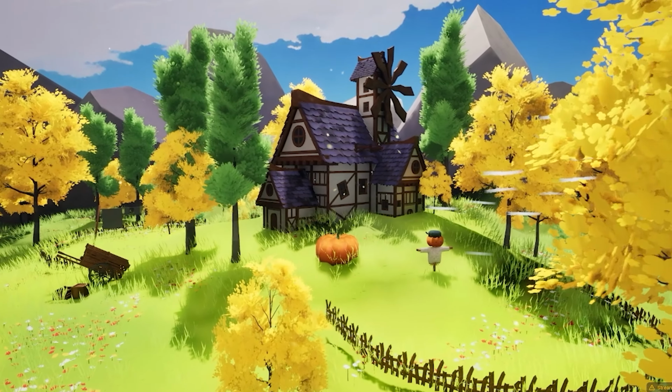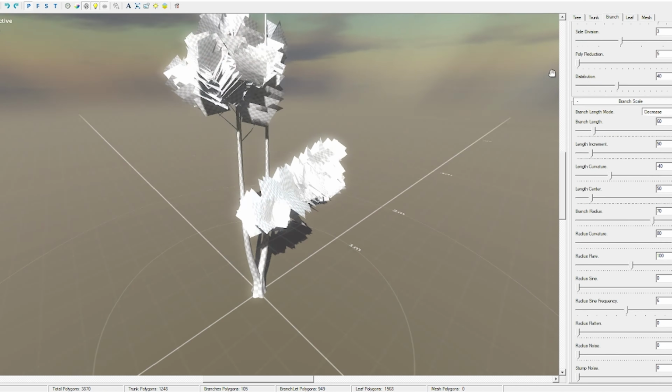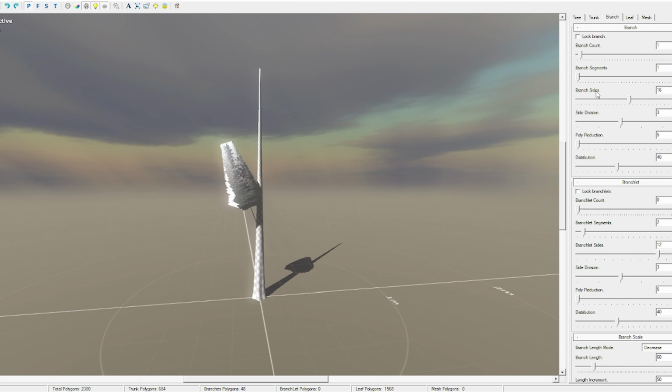With the first selection of trees up, I was able to copy and paste these nodes and invert the density filter to generate new points for the second lot of tree meshes. Luckily, with the first nodes already set up, all I had to do was retweak the settings again and add in the new tree mesh. To create the trees, I used the application Treeit to generate them. I wanted to go for a cypress style tree and an oak tree to fit my farmland theme.